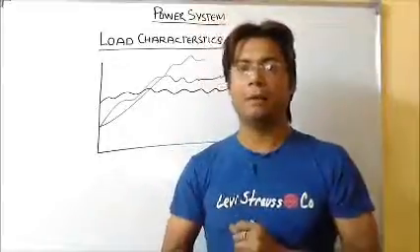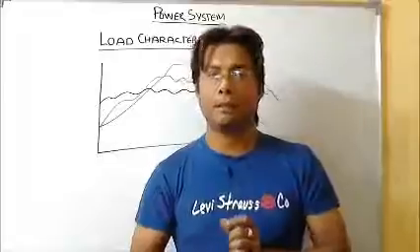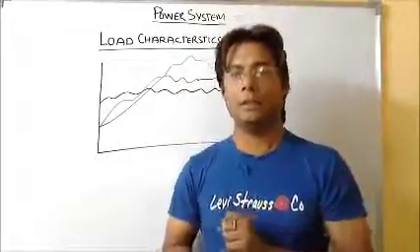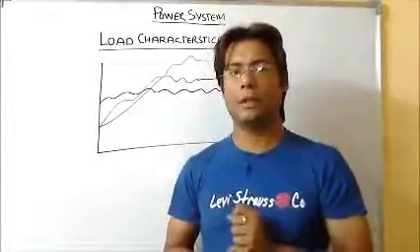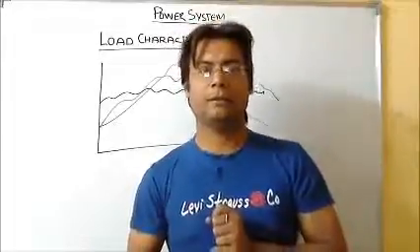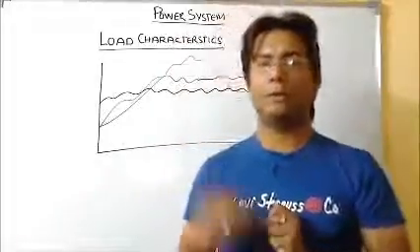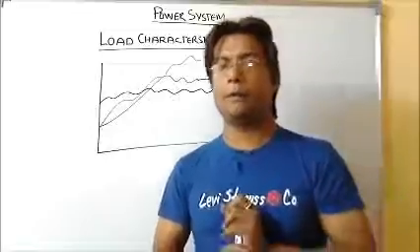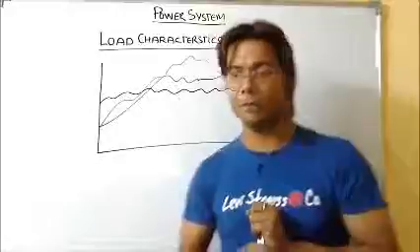And if I'm able to increase the diversity factor, if I'm able to increase the plant capacity factor, at that time the energy which is coming out of the generator, or which is coming out of the synchronous alternator, will be of a very low cost, and if it is of low cost, it will be economical for the consumer to use it. So the diversity factor and the plant capacity factor should be as high as possible.